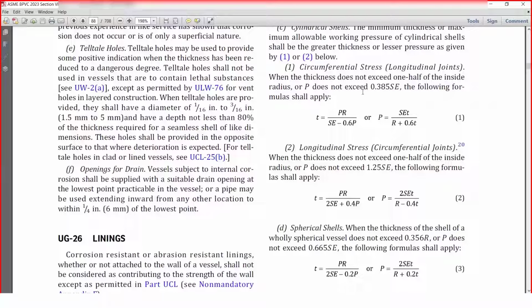In design pressure, if you look at the definition in UG 21, it has been written that we have to add static pressure in the design pressure. So the design pressure will include the static head at that particular location. Whatever pressure we calculate by this as a capacity, from that static head we have to subtract, and that term is called the MAWP of that particular component.